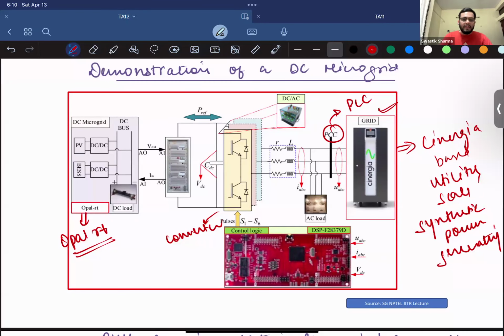Let's say that you want to trip a relay. The relay should be tripped fast enough, right? It's required in milliseconds. If the simulation shows 5 seconds, how will you test it in real scenarios, right? So for that, what you need is a real-time simulator.